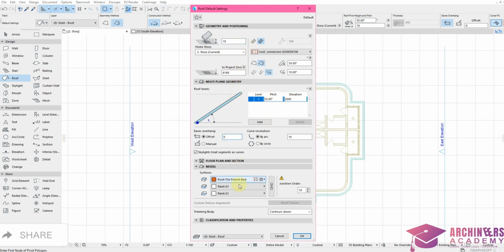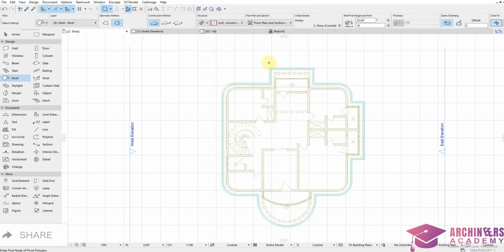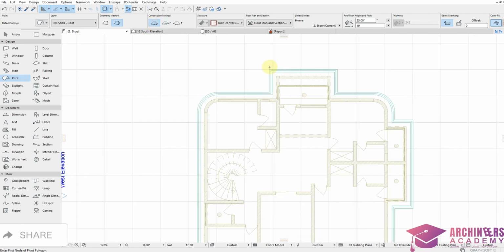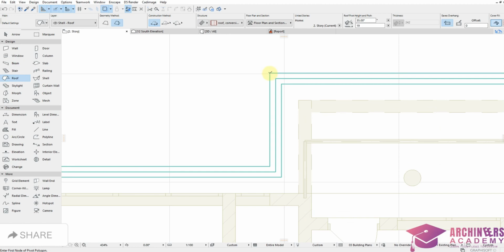You can change your model if you want. Your choice. You can also work on the angle of your roofing too. After you're done, you click OK. And we'll start placing the roof, just like how we placed the concrete fascia. Ensure that the roof construction method is on complex roof, because the building shape is irregular. Then we'll start picking the edges.